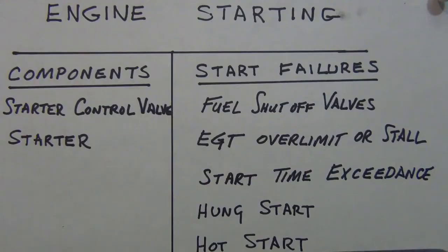All right. And as far as the duty cycle for the crank sequence, this is going to be 2 minutes on, 20 seconds off. Remember I said time to cool, so max 2 minutes for each cycle. There's four consecutive cycles. 2 minutes max, and then 20 seconds off for cooling, and then 2 minutes again.